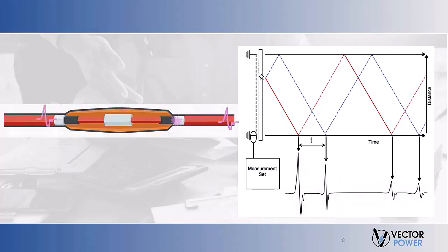Unfortunately, power cable systems are not perfect waveguides, leading to distortion of the pulses as they move away from their sources. This distortion is influenced by several types of cable system losses, which vary with frequency. The longer the cable system, the more significant the distortion becomes. The physical processes that contribute to these changes are well understood and include skin effect, dielectric loss, reflection, and radiation.